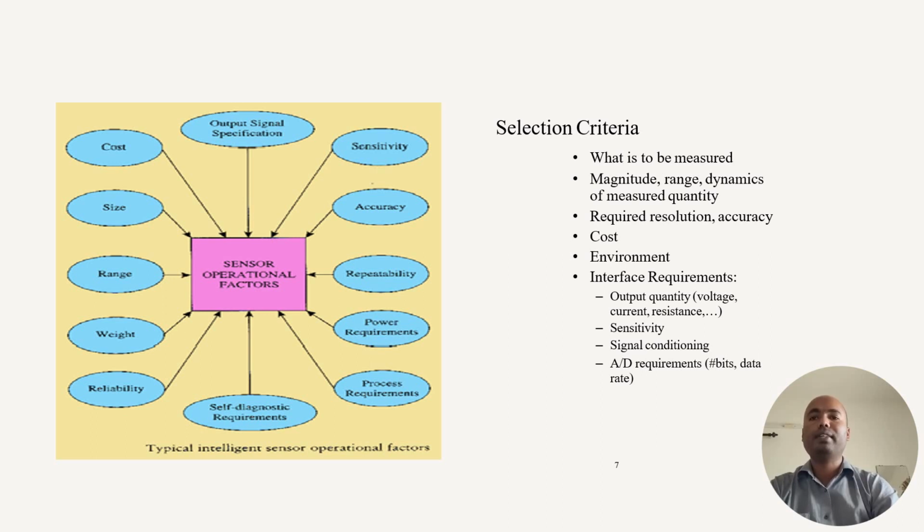A very good example is the O2 sensor, the lambda sensor. For working of the lambda sensor, previously it needs a process like heating the sensor up to 200 degrees Celsius. The lambda sensor starts to work above 200 degrees Celsius. So when the vehicle is in a cold region or the engine is started initially, by that time the lambda sensor doesn't work, and by that time it produces emissions. To avoid this, initially it needs a process to heat up these elements.